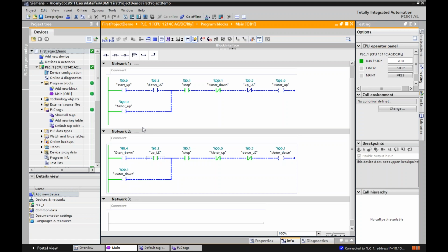So now I can close the garage door, hit that switch. It's going to get off that limit switch. I can take my finger off the push button. It's going to keep going down, down, down until it hits the down limit switch. Whoops, I got my switches mixed. There it is, down limit switch. But that's the concept. What I showed you, the basic motor interlock using limit switches to cut things off, that's the basic motor circuit.